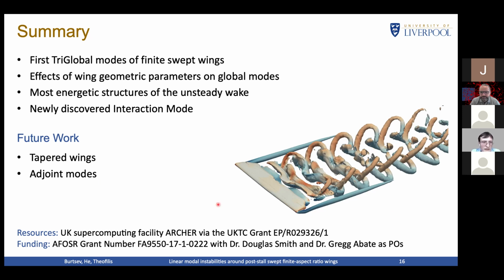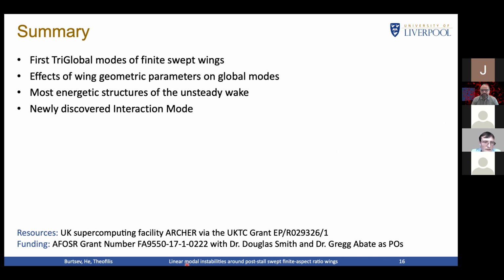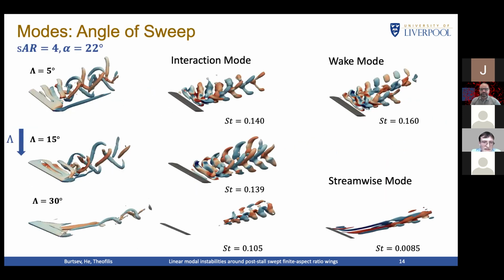Right. So with the elongated structures, I believe you refer to the modal data-driven results, the POD and DMD modes, right? That were at very low Strouhal. We didn't see those structures in the tri-global analysis. But then again, with time stepping, we can't really converge a lot of modes, typically probably less than 10, usually of the most dominant.